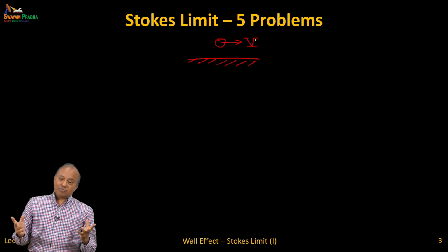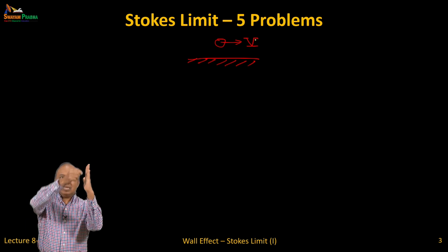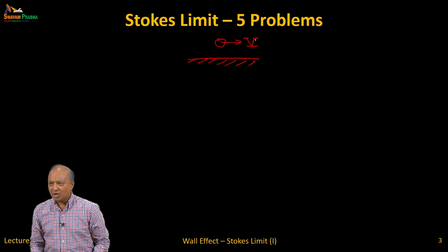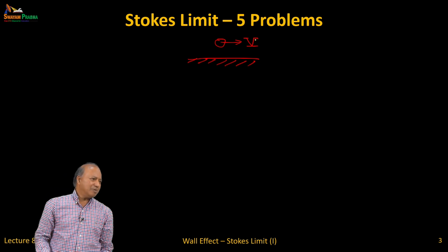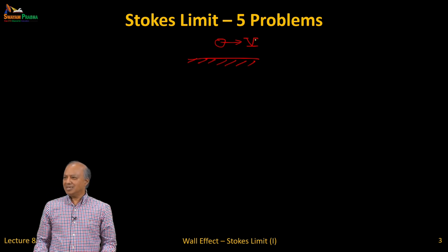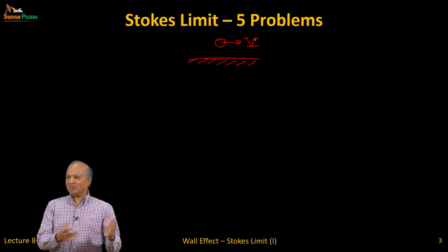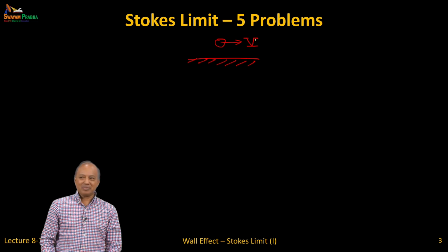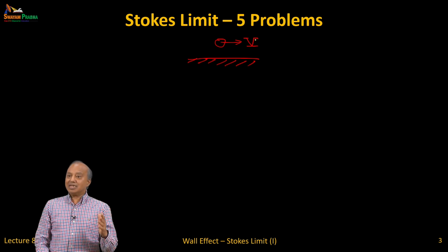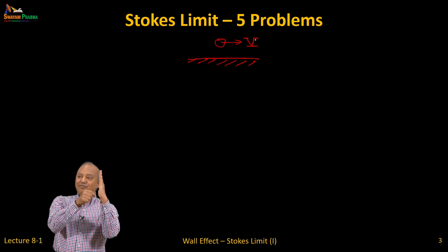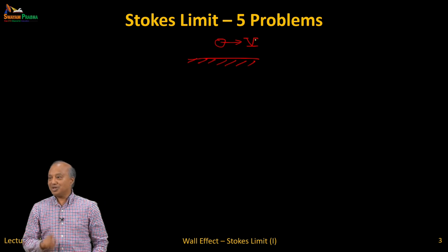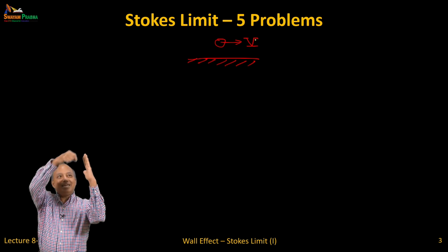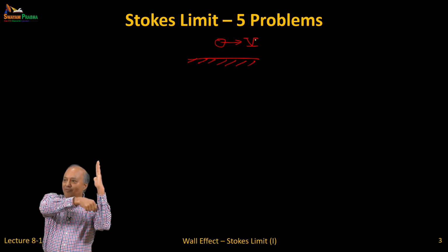First of all, one other question I will ask: close to your wall, the particle is falling, will its drag be larger or smaller? I think it will be larger because it's more viscous close to the wall. So how much? 5%, 10%? The other thing is, what will be the lift force? Now remember, there is no shear flow here. It's just quiescent fluid, and the particle is falling down.